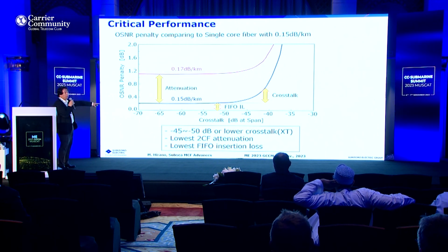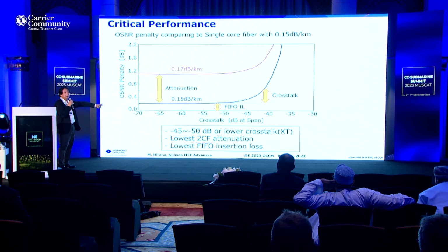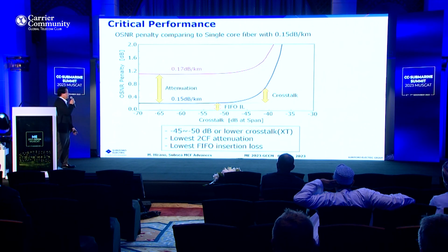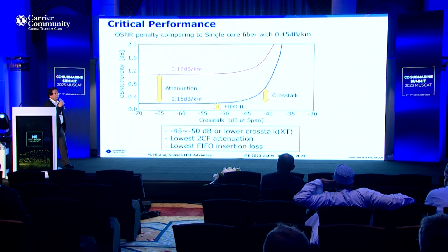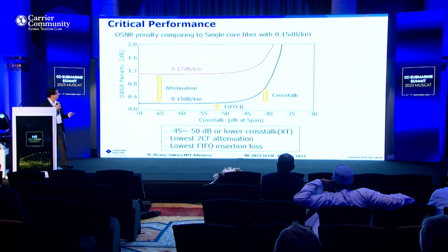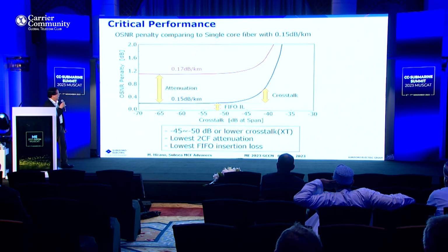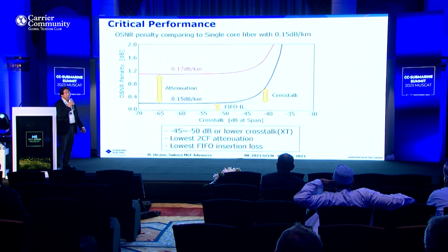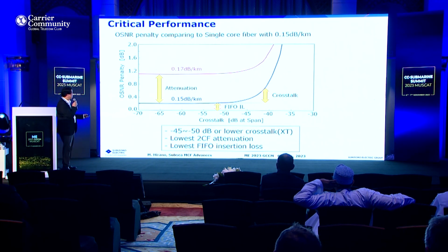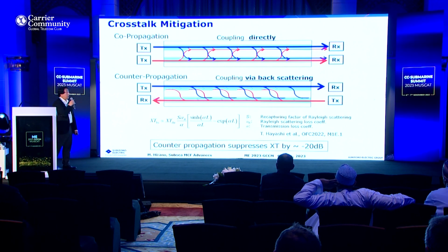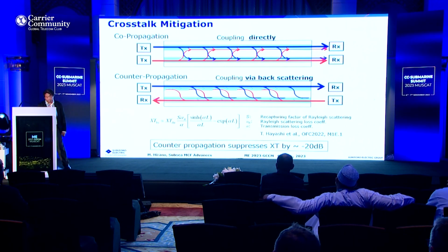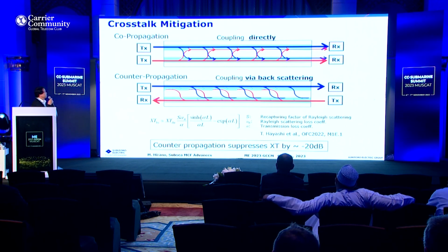And also, FIFO, this is a fan-in, fan-out device. Insertion loss will degrade the transmission performance. So the lowest FIFO insertion loss is another important parameter. Okay, so first, how to mitigate the crosstalk.